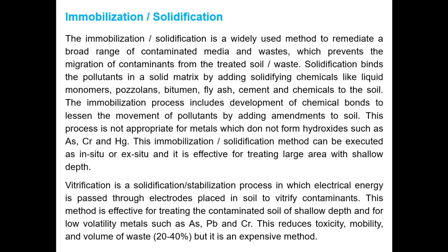The immobilization process includes development of chemical bonds to lessen the movement of pollutants by adding amendments to soil. This process is not appropriate for metals which do not form hydroxides such as arsenic, chromium, and mercury. This immobilization or solidification method can be executed as in situ or ex situ, and it is effective for treating large area with shallow depth.